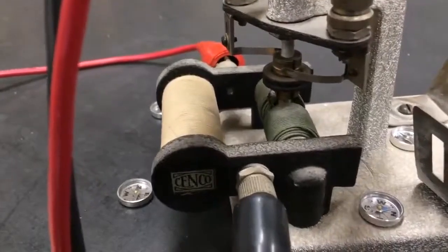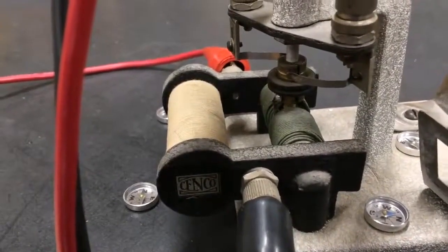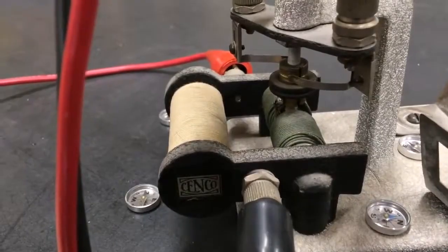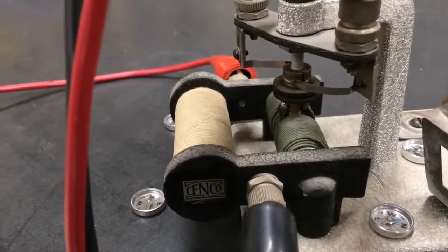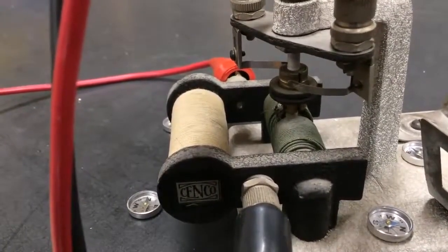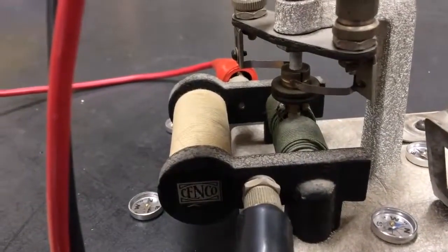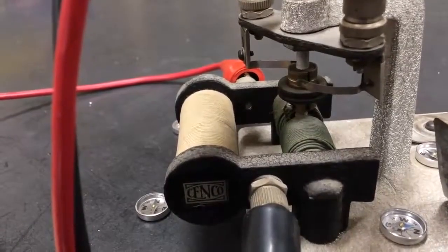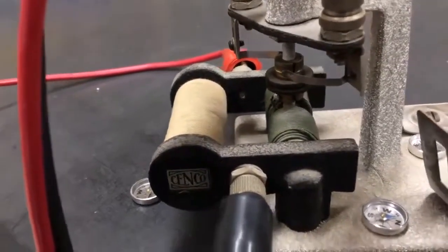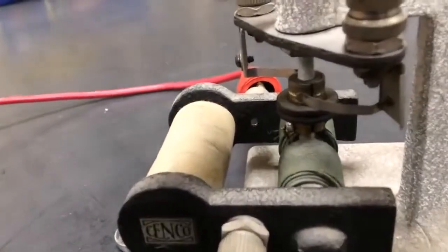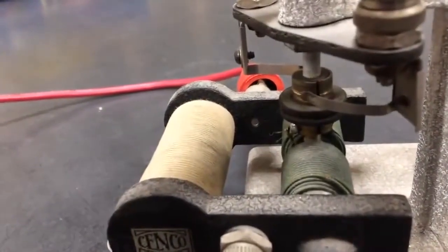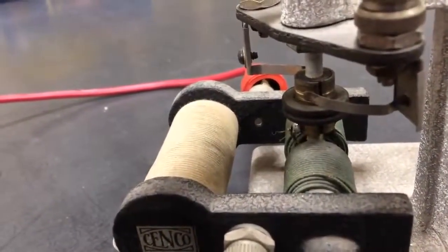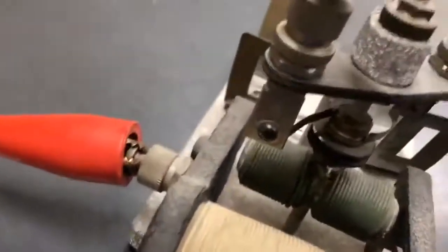So in the simpler motor you saw, the one from SciToys, we solved this problem by just having the motor be off half the time. The rotating part only made contact with its power supply 50% of the time because I only scratched off the insulation on half the wire. This has a much more ingenious solution. I don't know if you can see it, but that piece of metal is broken in the middle. It's broken on the other side too.